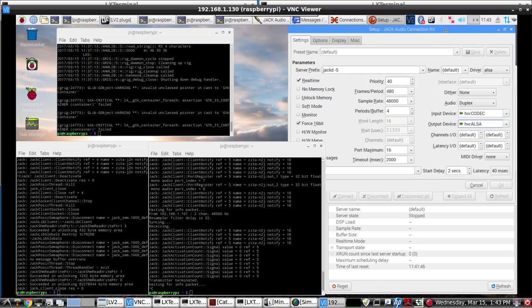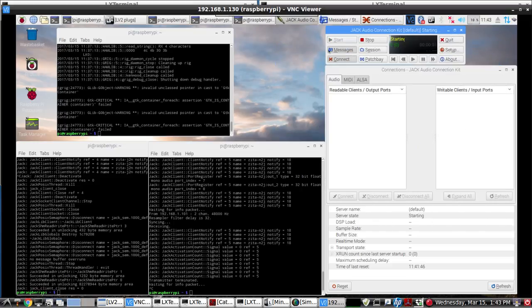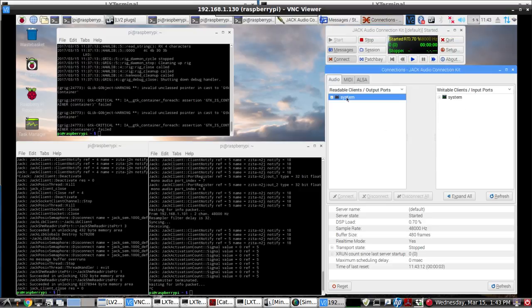So we'll go ahead and get started here. And click Start. And hopefully everything will go okay. There we go. So the system on the left is the incoming K3 USB audio sound card. The sound card on the right is what any of the directed audio will go to, that Raspberry Pi analog sound card, and then out with an audio cable that connects to the input of an audio-derived CW keying switch circuit. The output of that grounds the CW keying jack of the K3, just like you would normally do with a straight key. So we'll expand this.